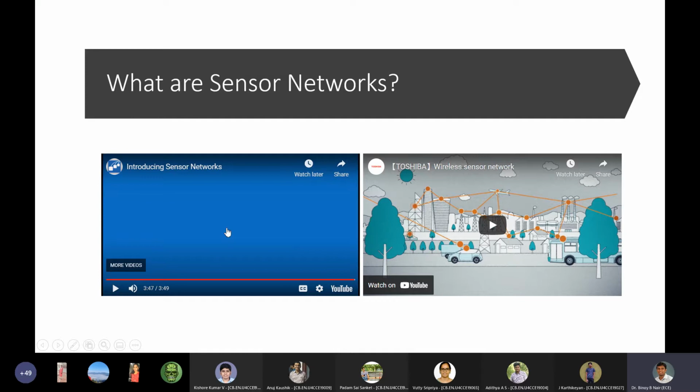So you have a multi-drop cable. That means a single pair of cables will be running, and you can basically tap into those wires and connect multiple devices. Up to 512 devices can be connected using RS-485. That's the protocol's limitation: you can connect only 512 devices at the best. And one more thing: what do you mean by multi-drop?